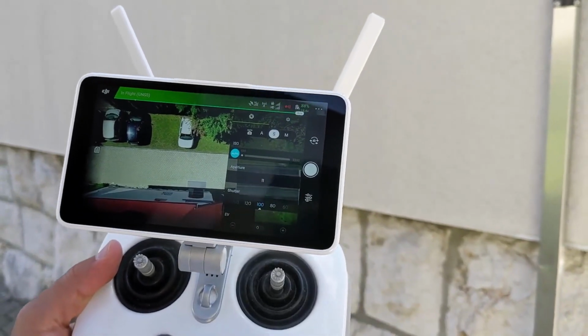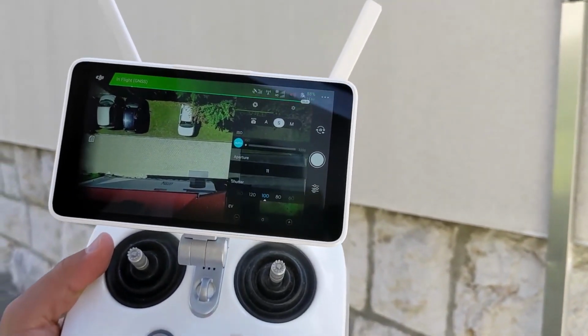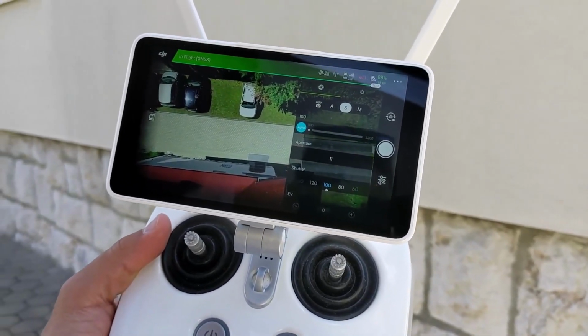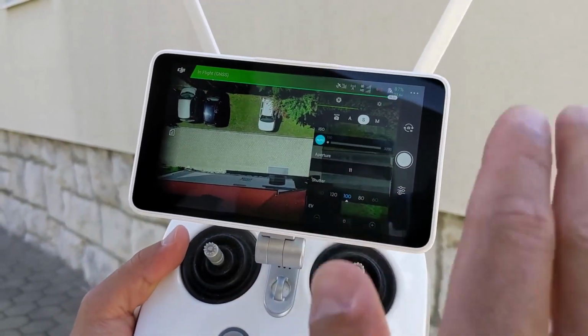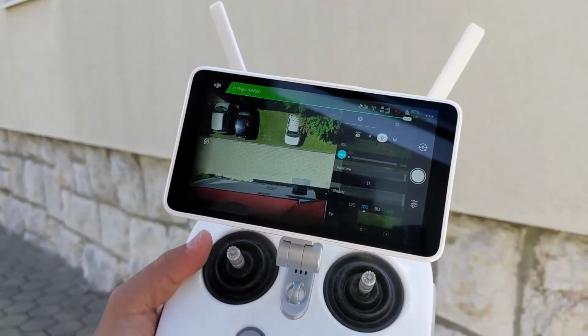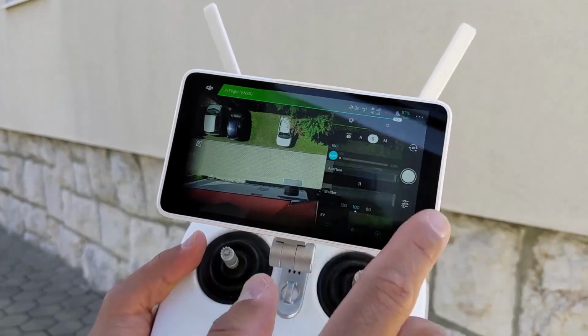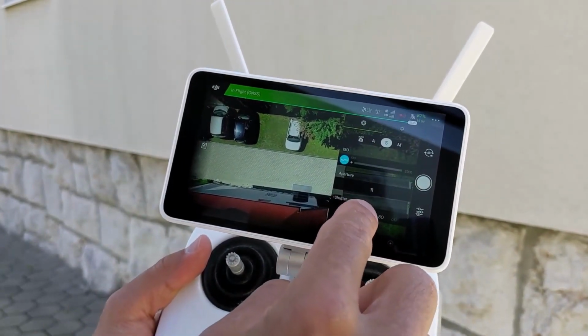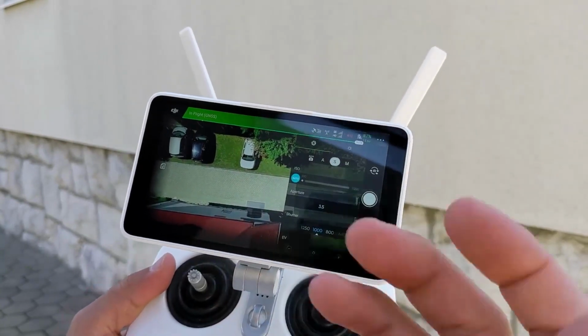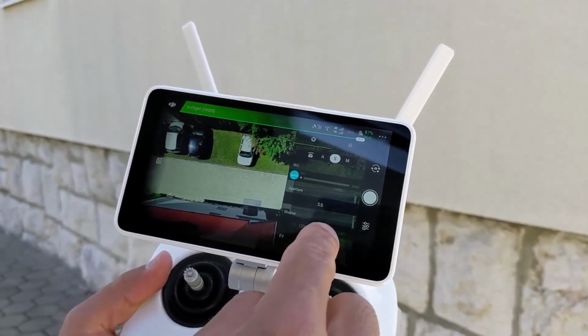You would definitely like to have an ISO value of 100, because this will give you the best accuracy of the model. The aperture can run from 2.8 to 10 or 11. Currently it's 11, and shutter speed should be between 100 and 2000 or something like that, depending on the weather condition you currently have.